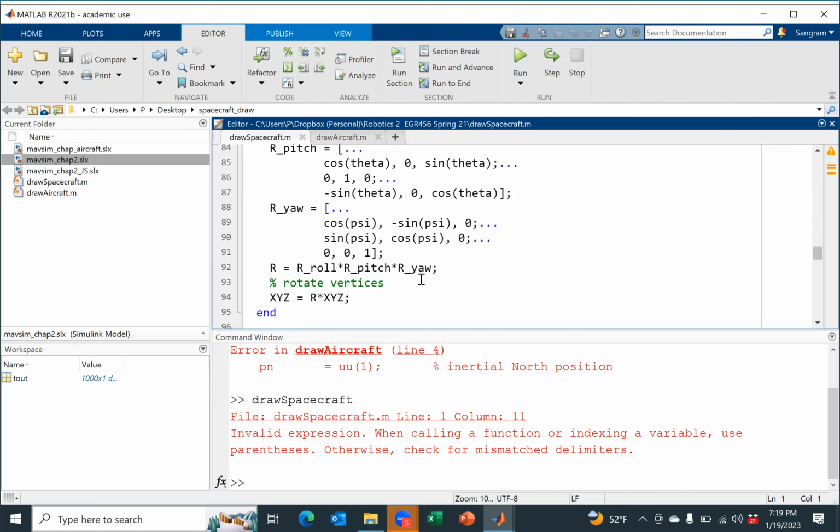First, we are in the vehicle frame. First, we have a yaw rotation, then we have a pitch rotation, and then we have a roll rotation. So that's why the first matrix on the right hand side is yaw. That gets multiplied with rotation of pitch. That gets multiplied with rotation of roll. Everyone understood this? Because we are going from the vehicle frame to body frame. Vehicle to vehicle 1, vehicle 1 to vehicle 2, vehicle 2 to body, in that sequence.